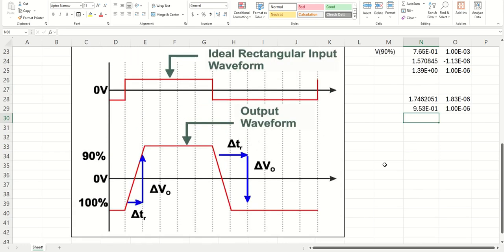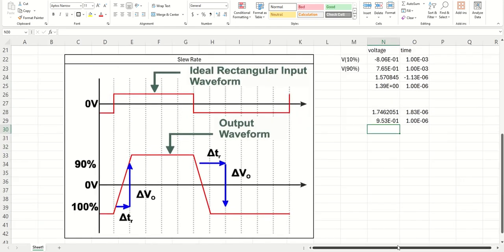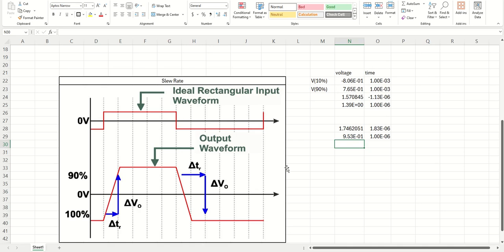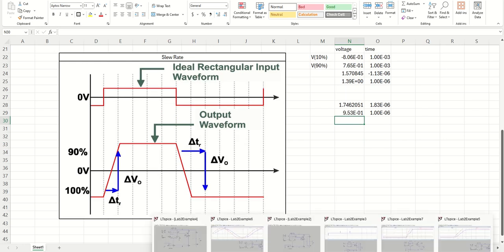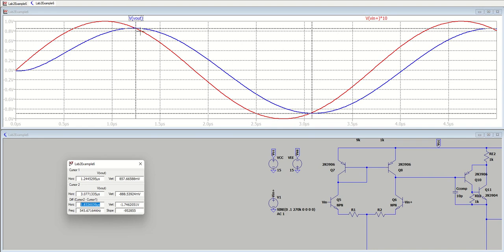Okay, so there's another way to do this if you don't want to try increasing the frequency. I think increasing the frequency and measuring the slew rate experimentally is very easy when you can see the linear distortion. But since we don't actually see the triangle wave or linear distortion on the output, it gets a little tricky because you have to measure the 10%, 90% portion.